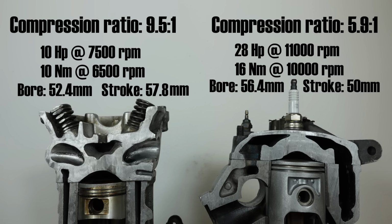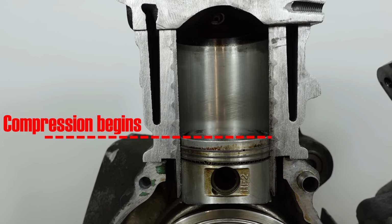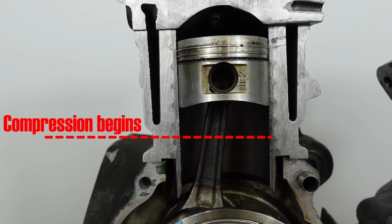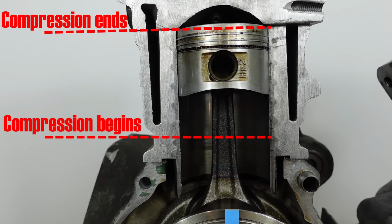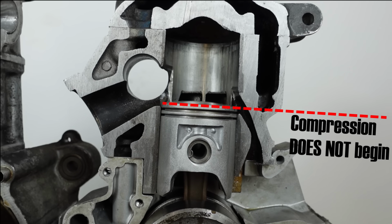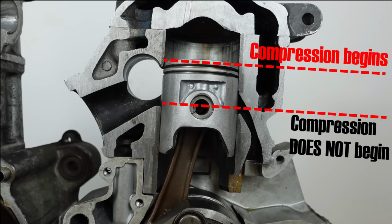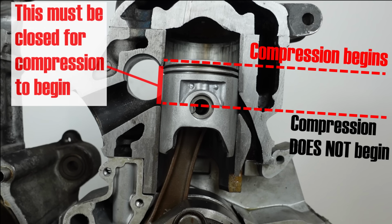Why is this the case? Well, the reason is very simple, and it's because the 4-stroke utilizes the entire volume of the cylinder. Compression begins when the piston is at bottom dead center and ends when the piston reaches top dead center. Things are different in the 2-stroke. Compression does not begin at bottom dead center. Instead, it only begins when the piston closes off the exhaust port. Before the exhaust port is closed off, the cylinder isn't sealed, and air and fuel can't be compressed. Instead, they're free to escape through the exhaust port.